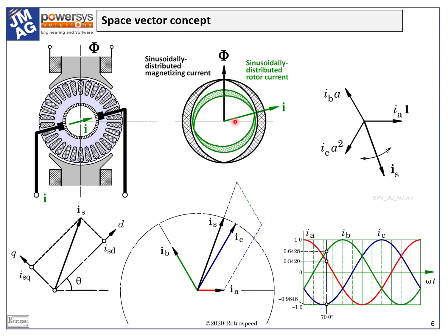We will see that there is a space vector for each phase winding, and another space vector that combines the effects of all three phases. In the induction motor, we will find a similar set of space vectors for the rotor as well. In a typical AC machine with three phase windings, we have a space vector for phase A, one for phase B, and one for phase C. Each one of these is stationary in space, but its amplitude is proportional to the instantaneous current in the respective phase winding.